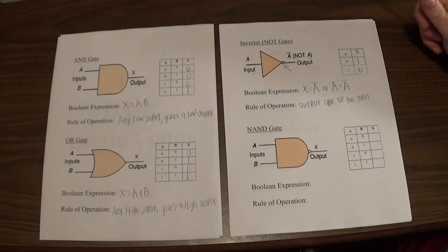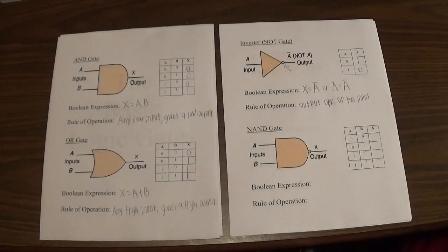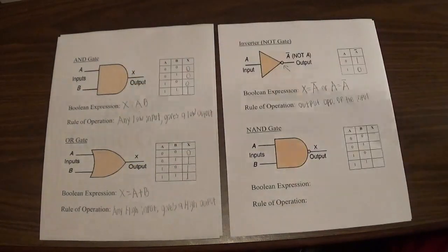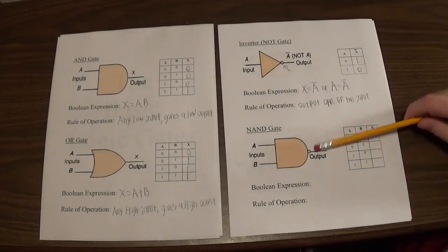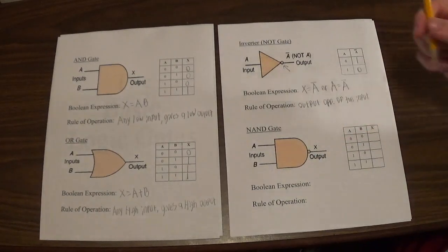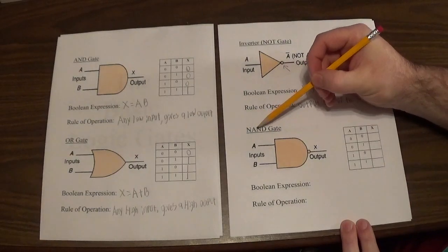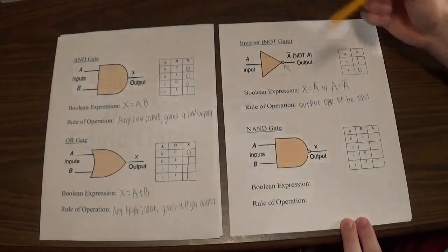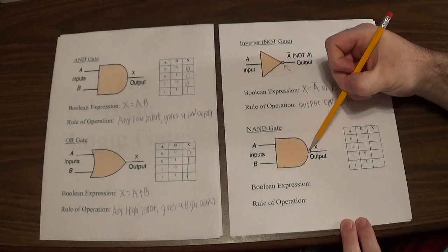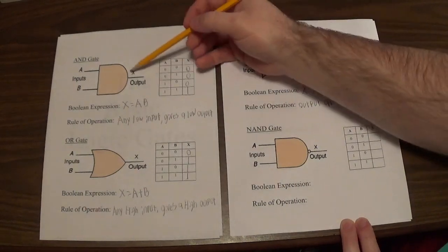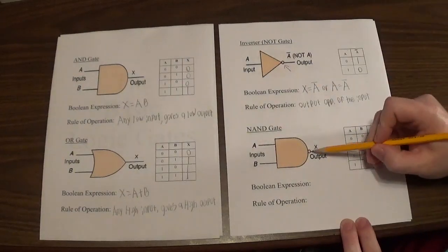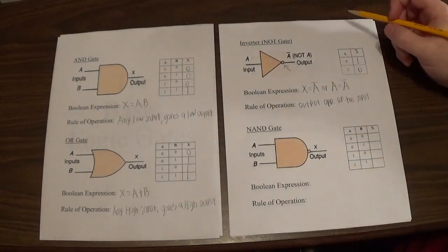All right, so the next one is called the NAND gate. So those are your three basic logic functions. So everything else kind of just derives from these three. All right, so the next one is called the NAND. So that basically means not and. So it's an AND gate with an inverter connected to its output is basically all it is. So the symbol you'll see is basically the same, except we have the circle on the output, and that makes